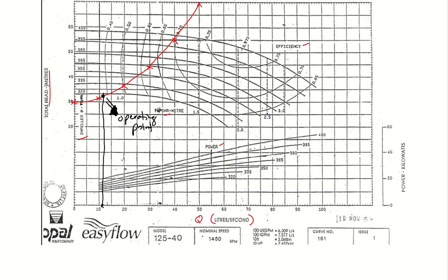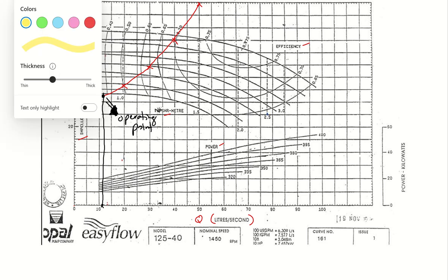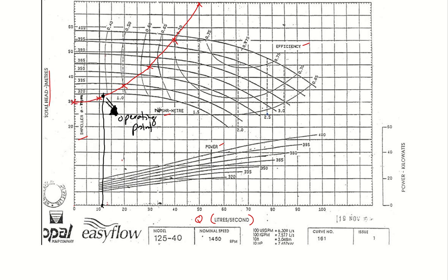So the question wants to get the impeller size. If you look at the chart, this is the value for impeller size. Since we don't have a line here, but the line is very close to 320 millimeters, you can actually assume the value for impeller size is approximately, so if you look here, I choose 318 mm.